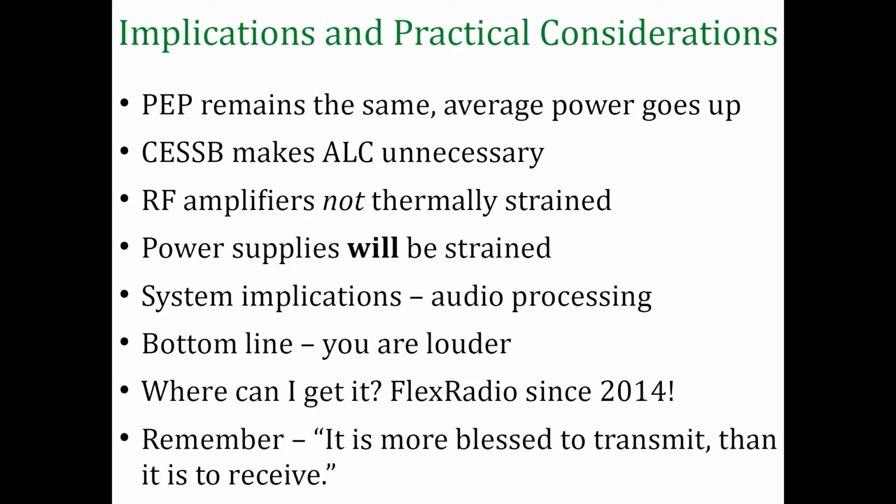Modern broadcast-type multiband limiting and distortion-canceled smart clipping can be applied with much better results than a simple wideband RF clipper. So I think we will see the development of some very good speech processing algorithms which can be combined with CESSB for no overshoot. Bottom line, your sideband signal will be louder without sounding more processed.